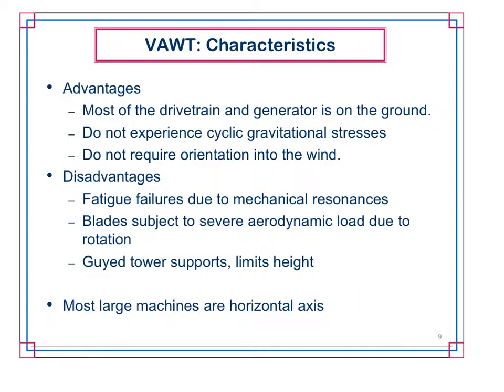So there's a practical limit as to how far up you can go, all right? And that's because if you think about a tower, right? You have a tower coming down, you have to make sure your guys are far enough outside here so as these blades are rotating along, they won't hit onto the guy wires. So you have to angle out pretty far, which is not a big deal, right? You can get to extreme lengths, but the problem is you have to lease the land that these turbines are located on. So if you're getting to massive, great distances, then there's additional costs for you to lease that land.